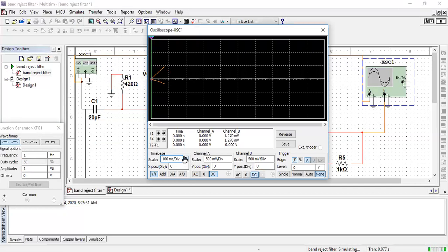You can see that your channel 1, or your first channel, I have put at 50 millivolts, and channel B also 50 millivolts, both on DC, and the time base you can just vary, right? 1 second or 50 millisecond or 200 millisecond, and you can observe both output and input here, right? So this is your output and input both here.